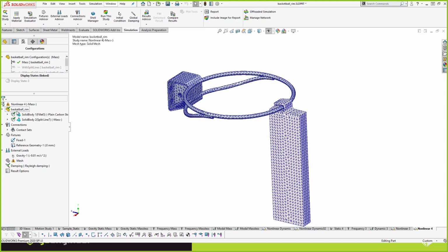The linear dynamics study, the modal superposition method, is very elegant and works very well when applicable. It works well for linear problems where you're not changing things in the middle, like removing masses. But if you do need to have things changing in the middle, we might have to use the more direct method, nonlinear dynamic, and it can take a lot longer to run.